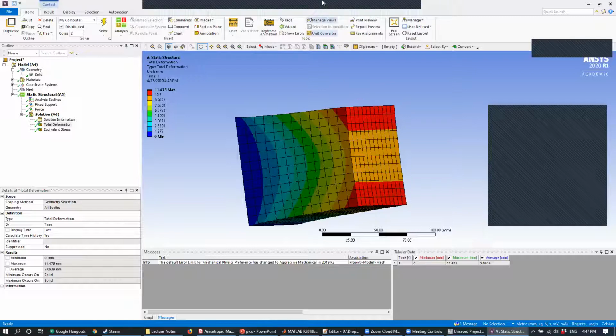Okay. So I would say the only thing I would be careful about, if you are loading material properties from Solidworks, and I don't know if Solidworks does this, is that if you're doing something like wood, you want to make sure the grains run in the direction that you want. So just be careful about that, and make sure the strength is high in the direction that you want, because when you do orthotropic materials, the direction is really, really important.